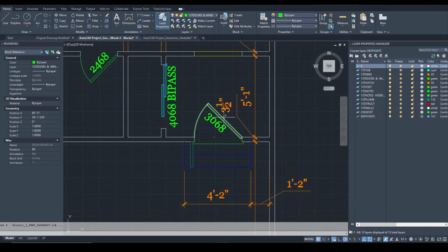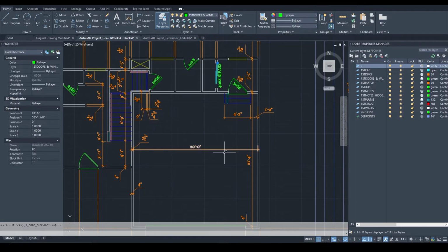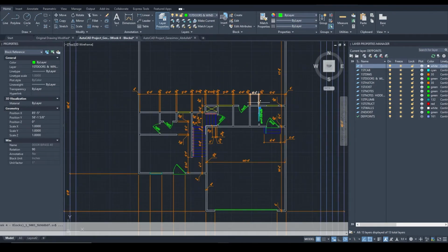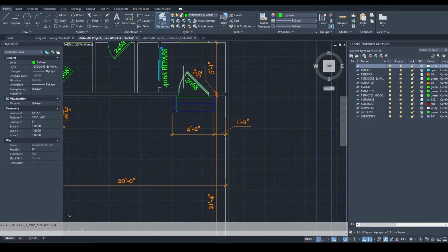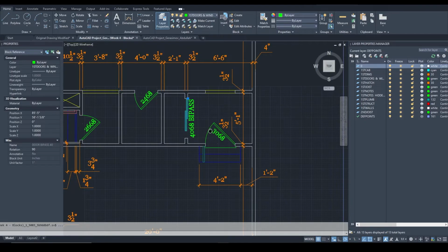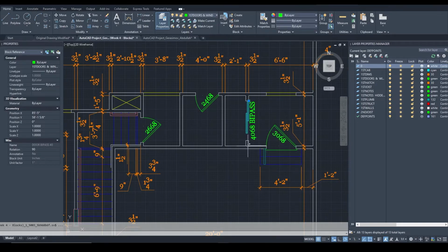This door is going to be a 3-foot door, since it is going to be going into the garage. The reason for different sizes of doors and their width is primarily because of their purpose. When it comes to the garage, typically if you have any sort of belongings that are very large, you want to be able to put them in the garage, and the wider the door, the easier it is for you to do that. But you don't have to have a 3-foot door everywhere. If you have a small powder room, a 2'4" door will suffice just fine.